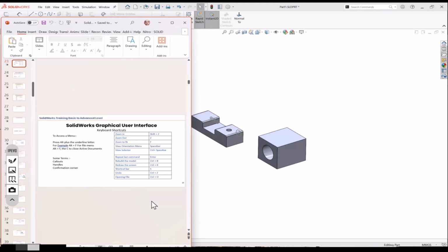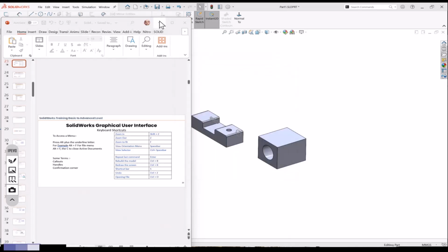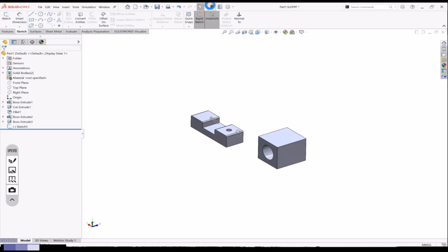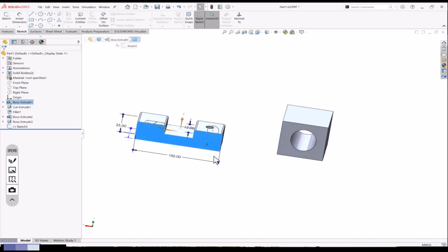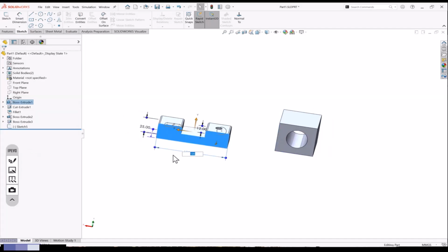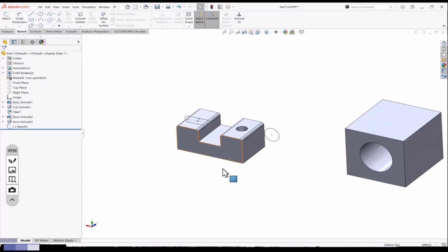So will it remove the error if we click on that dot? It does not show an error actually, it will update. It just updates the model. Right now nothing needs to update. But sometimes if we change a dimension, it does not change. For example, you made it 40, but the actual model does not become 40. In that case you just click on that and it will update. If it is not possible to make it 40, then the software will make an error.